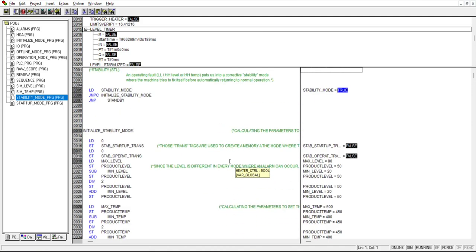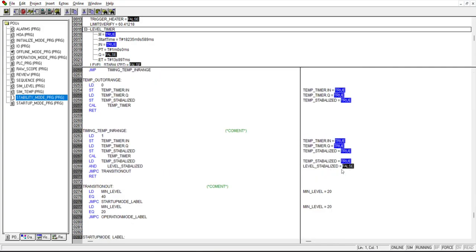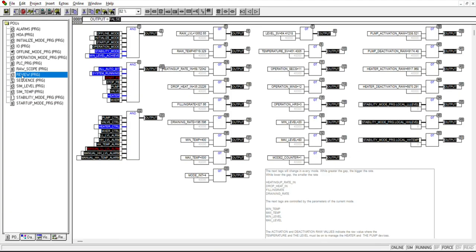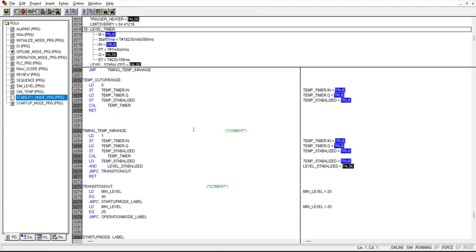The manual alarms simulation tags are programmed within the main POU in structured text. This logic bypasses HOA controls to activate or deactivate specific devices for testing purposes. For instance, to simulate a low-level alarm, the manual alarm tag deactivates the pump and activates the valve to rapidly decrease the tank level.